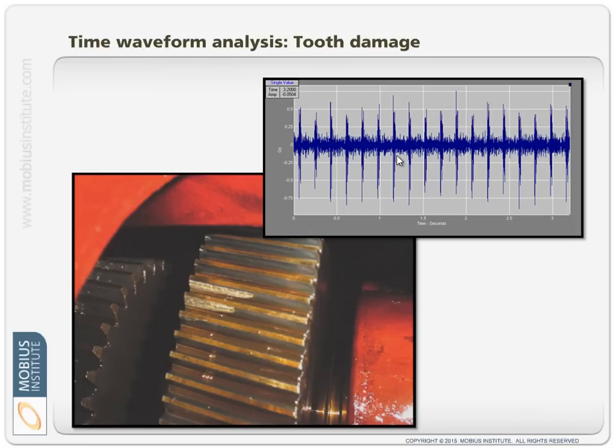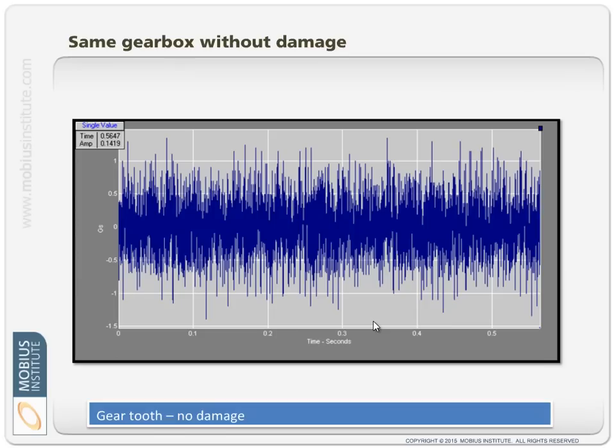And there are some cool ways that you can look at time waveforms. Well, I think it's pretty cool what we're seeing here, but you can mark it off in revolutions of the shaft. You can look at it wrapped around a circle and see that once per revolution it's occurring. All really cool techniques, but it's telling me exactly what's going on. By the way, we should do oil analysis as well, because the pieces of metal would go into the oil and we could detect that. So, very useful technique in parallel with vibration analysis with gearboxes.